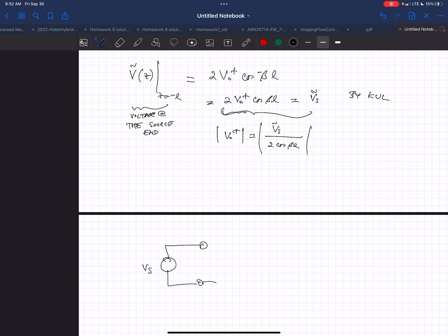It's zero resistance output. Not a realistic scenario, but usually they're low resistance. Voltage sources in the lab are probably 50 ohmish or maybe 5 ohm, depending on what you get. They try to make them low resistance sources.